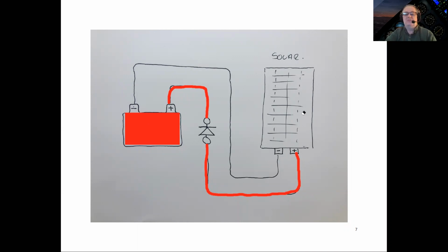The solar collector will actually become a load to the battery. And so through the darkness, you would actually lose your charge and it would be going back into the collector and dissipating off. So this really is like a backflow prevention.